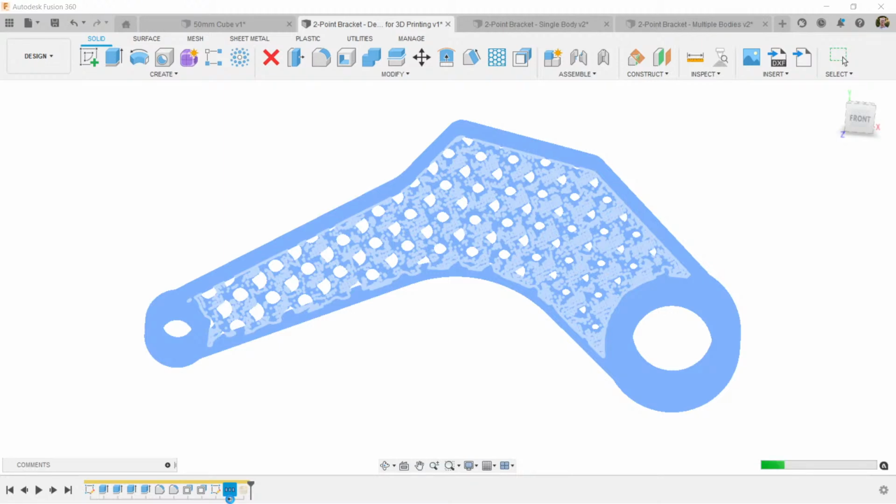So the mesh file that you create in Fusion 360, you can output as an STL, an OBJ, or my preference would be a 3MF file. And let's kill this screen because this is of course just watching water boil, which isn't the most fun. But you can take that mesh file type and you can of course go and 3D print it.